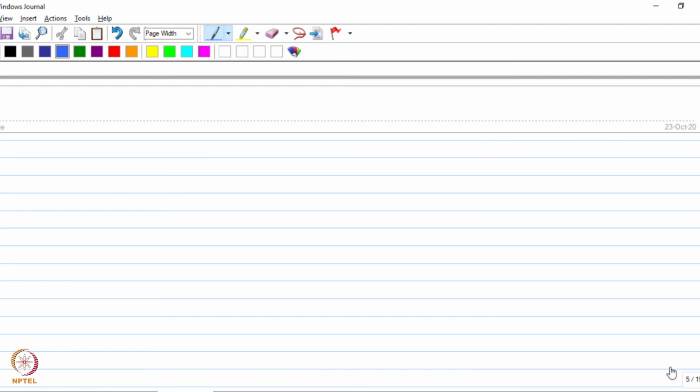So in the liquid metallurgy route, we have another technique called melt infiltration. In this process, the reinforcement is first assembled to make a porous preform.